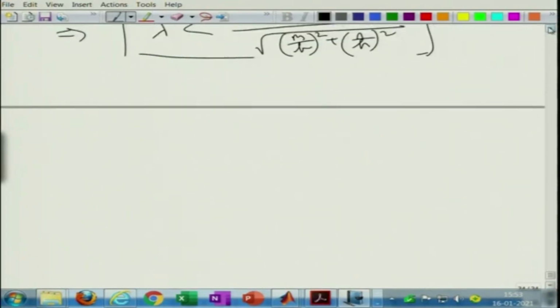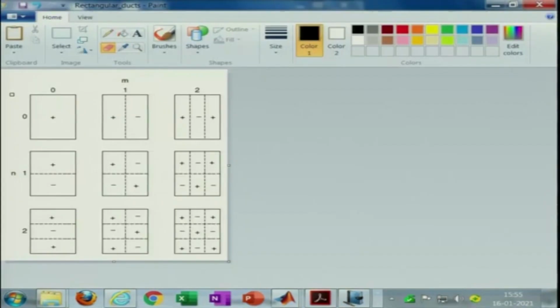Now, there is another concept that needs to be done, that is the volume velocity concept. For that we have to understand the velocity along the z direction, but before that let me present to you a figure which shows the modal distribution or the mode shapes of a rigid walled rectangular waveguide. So, clearly this is your plane wave mode. Across this rectangular cross section, as we promised, this is your b and this is your height. So, across this cross section your acoustic quantity is constant.